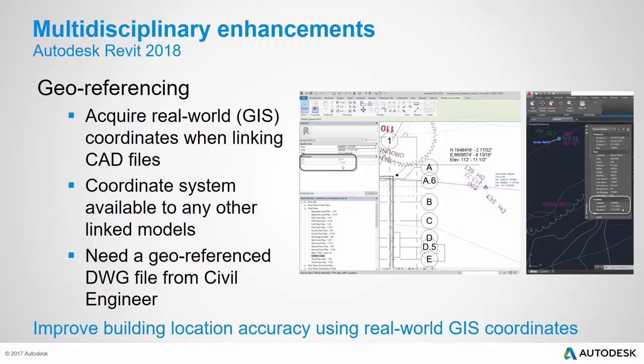Well, while working in that architectural site model, getting the coordinates specified was always a big hassle, right? The structural or civil engineer had to give you a certain file, export it with certain data, with an AutoCAD tag that told you the northing, easting, and elevation, and then you had to do all kinds of steps inside of your file to get it to work out.